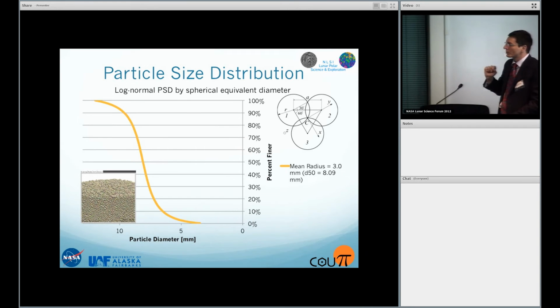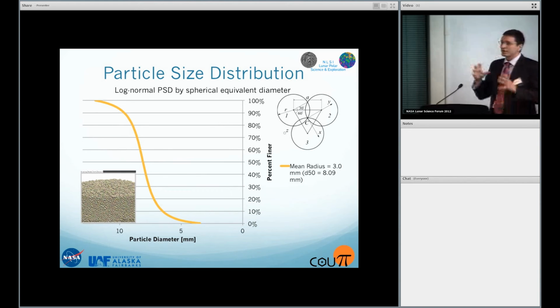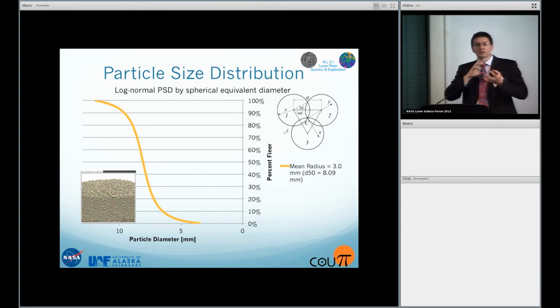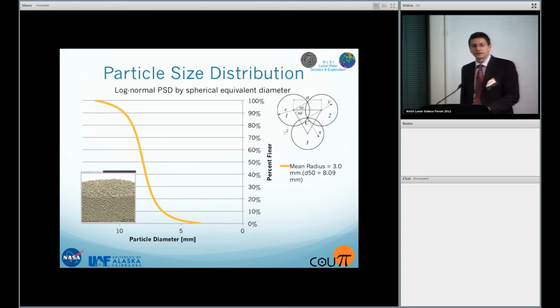This shape is very easy to compute, computationally very efficient. On the other hand, it represents some sophisticated behavior of the soil, like interlocking between particles. And as I mentioned before, it also has very nice analytical formulas for moments of inertia and other things that you need for the simulations, without doing it numerically.